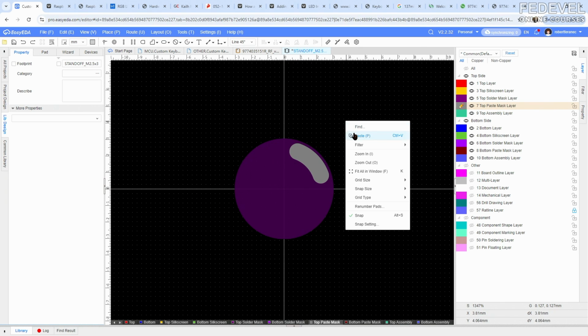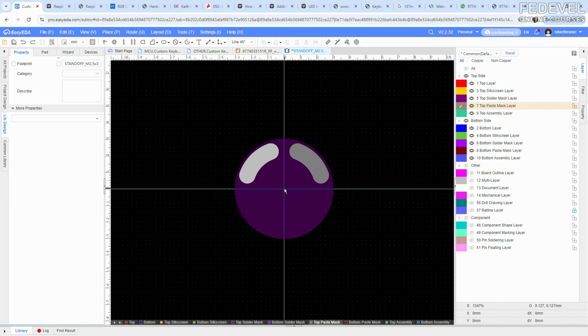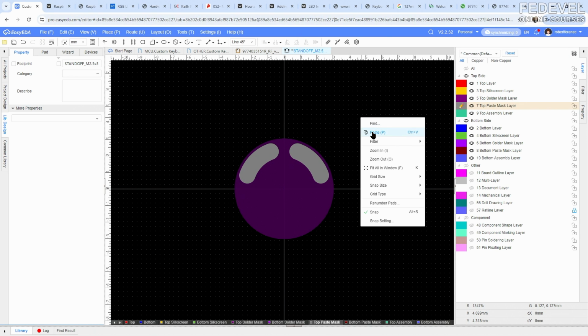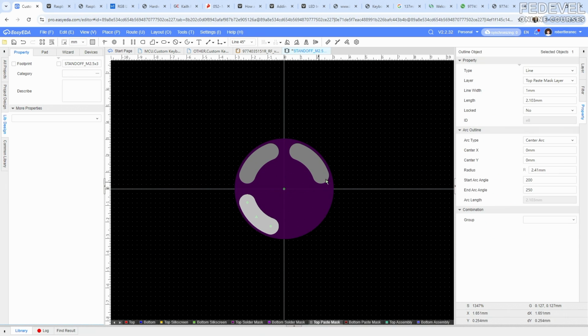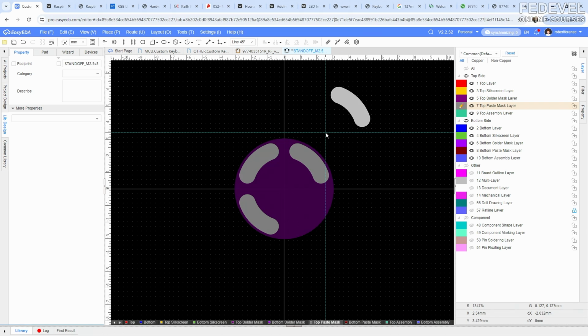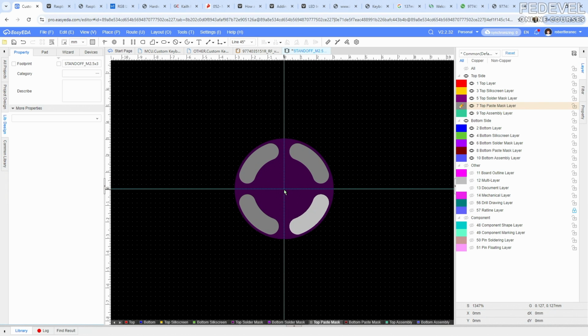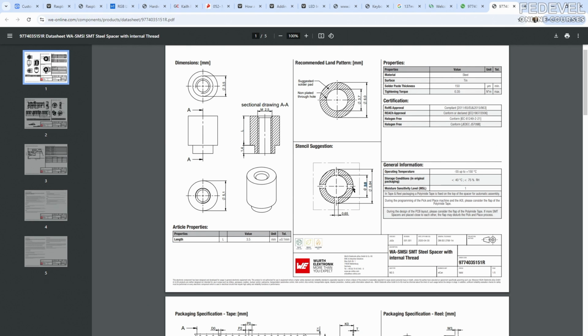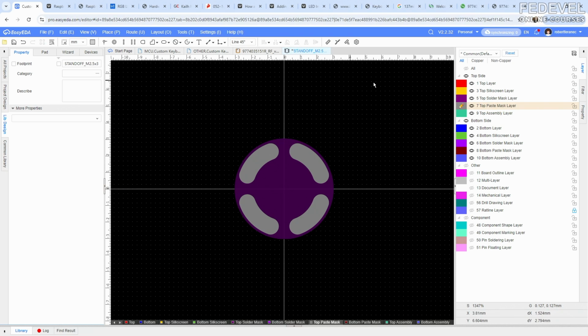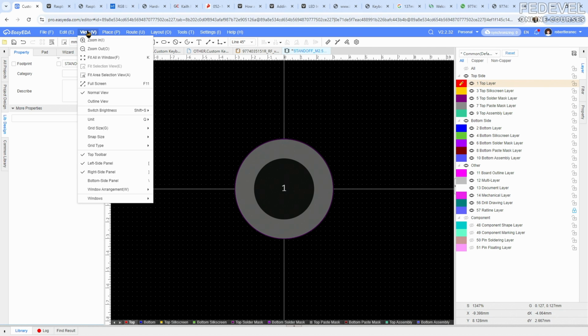Copy it from the middle and then paste it into middle again. This is very important. Always when you do copy in this PCB or in the footprints, it will also ask you where you would like to pick it up. So this time use the 0, 0 position. Compare it. It looks perfect. It looks exactly like it is recommended. So we can save it.